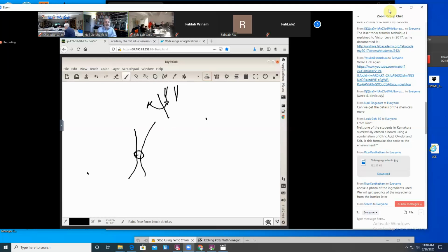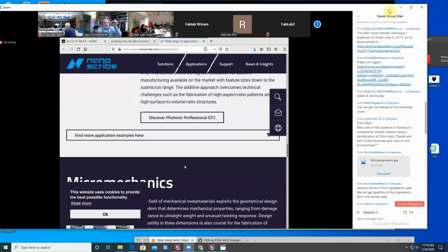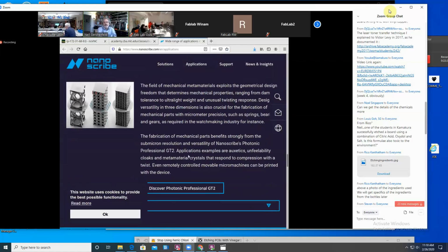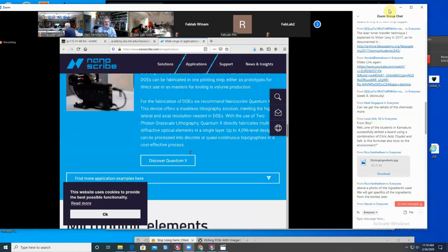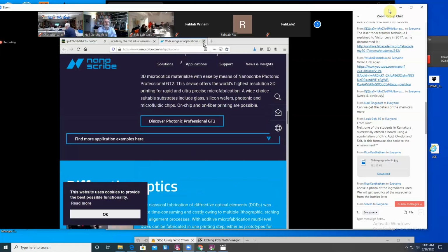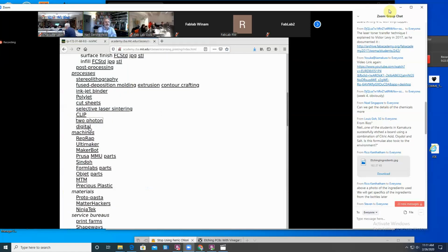In a 2-photon process, you have 2 laser beams, and physically, you need the energy from one combined with the energy of another to make the chemical reaction. And so the reaction happens where both beams are, and that gives you a significant resolution enhancement. So this is limited. The biggest part you can make is down to millimeters, but it lets you make micron scale parts to print the very tiniest parts that way.